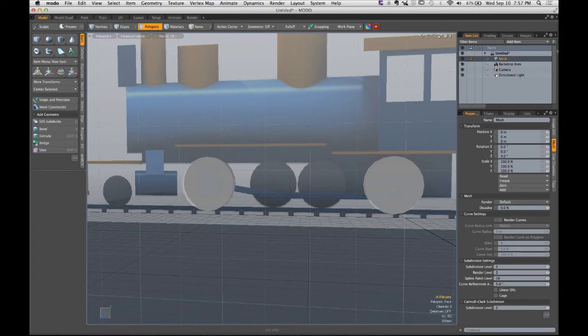Without a mesh item, you can't draw any polygons. Help her out. How do we add a mesh item? Did any of you guys stumble upon it? Yeah, you got it. Add item. And it's right below, there it is, mesh. Once you have a new mesh item, you're on your way. So be careful with when you're hitting that delete button, okay?